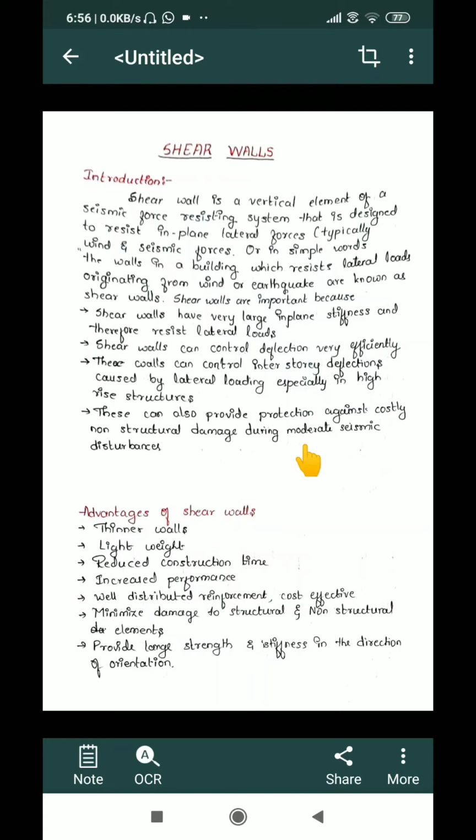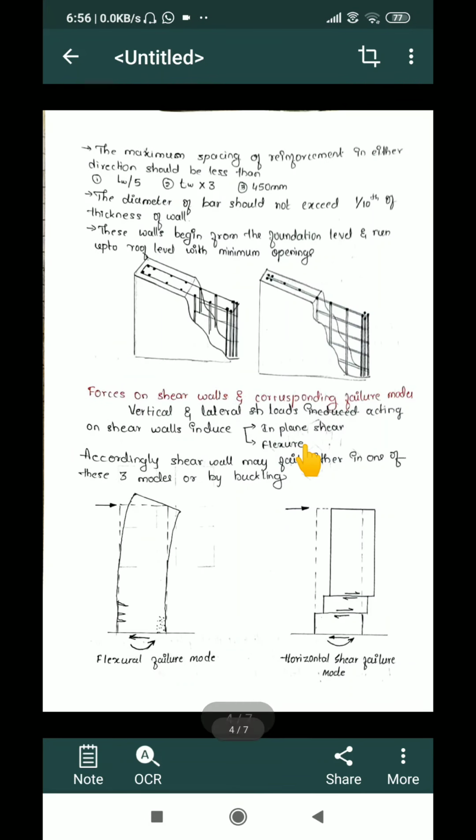To explain these important points, I would like you to consider this building. So this is a tall structure, any kind of tall structure, and there is a lateral load or a horizontal load applied on the tall structure. As soon as the load is applied, the building starts to deflect in the opposite direction of the load. So when this building deflects, there will be a number of stresses, strains and deflections caused in the structural material of the building.